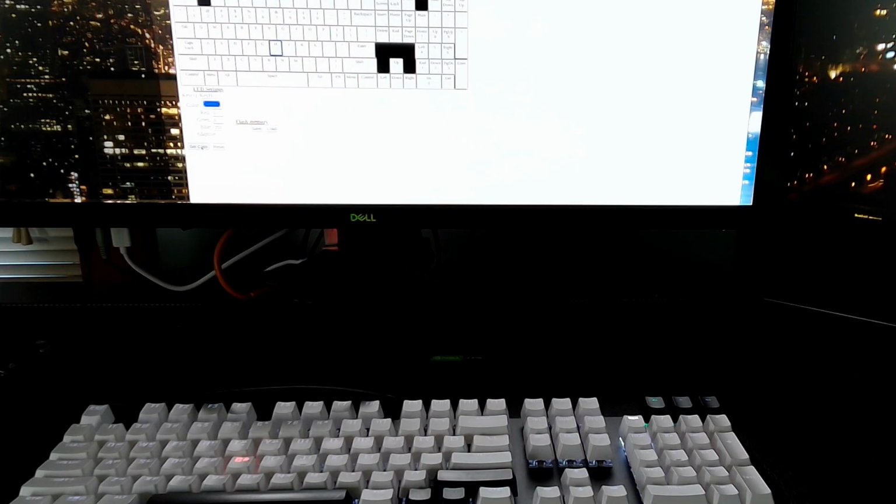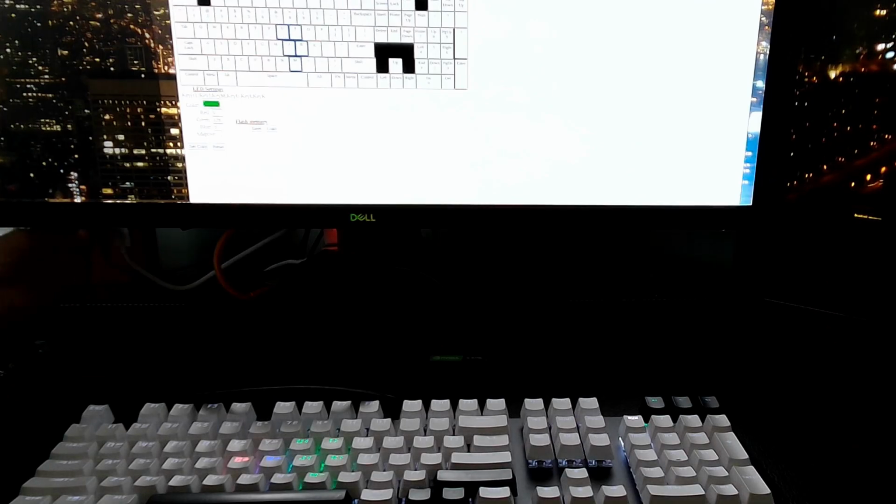And at that point, I can go ahead and set the colors of individual keys and save them into RAM or into temporary memory. But that means that whenever I unplug the Pico 2 and it loses power, it would lose those settings, so that whenever I plugged it back in to give it power again, it would reload the default colors instead of the last used colors. So the last step here is to save the color configuration from RAM into the persistent flash.